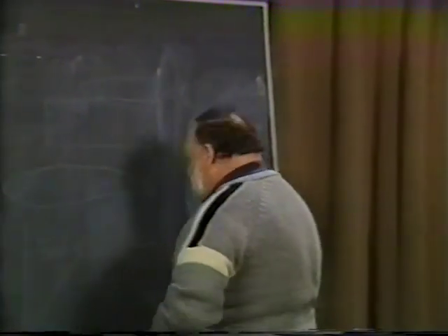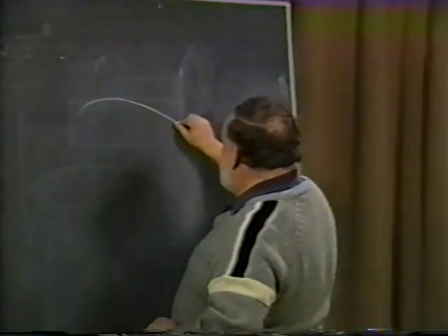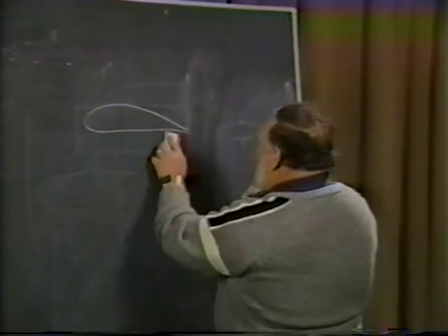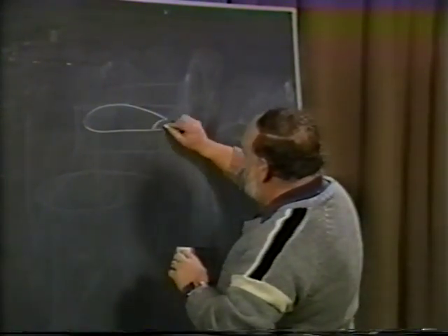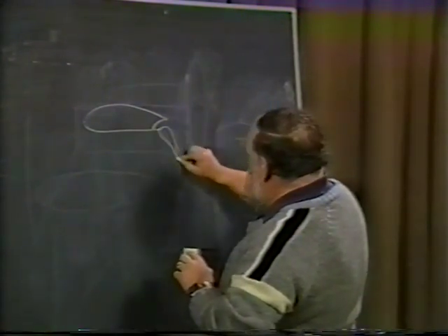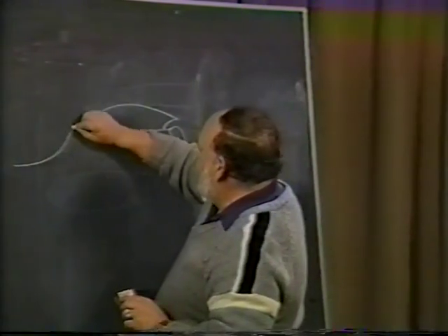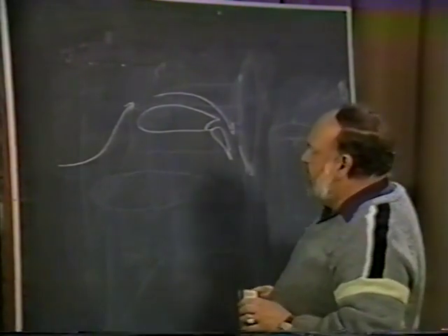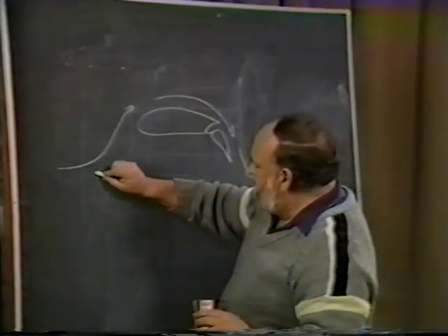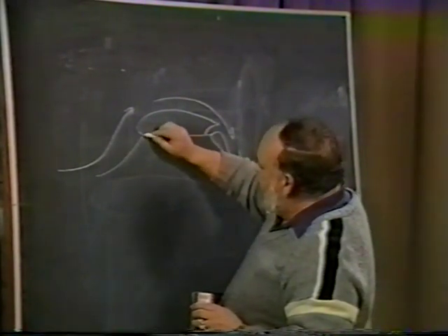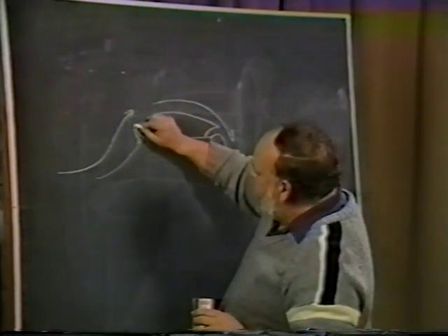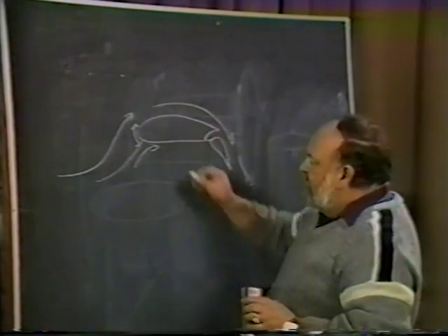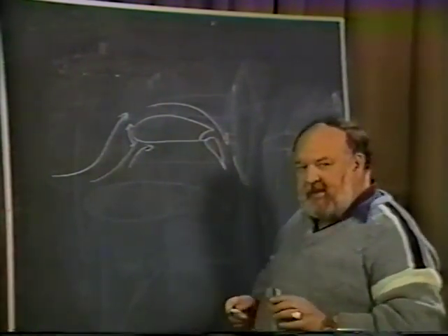If you have your wing like this, and if you have really good, powerful flaps built into it, to where you will be pulling in a great deal of air over the wing and producing really high CLs, then your stagnation point, the point where the air comes along and hits the wing, and on one side of this point the air goes around the leading edge, and in the other case it goes under the wing. Where this stagnation point is, is something you have to be aware of.